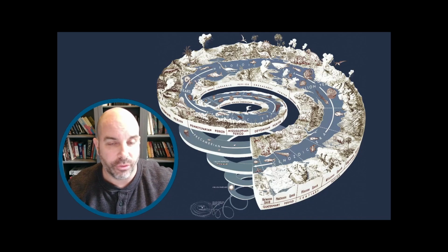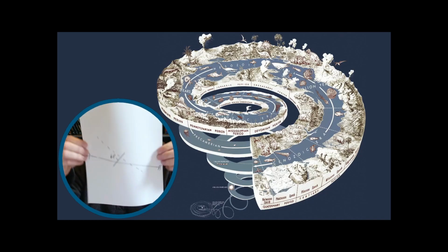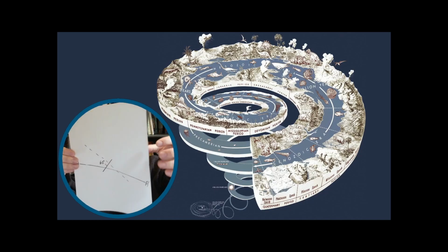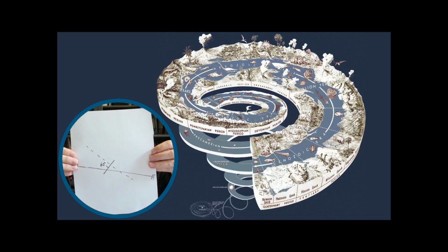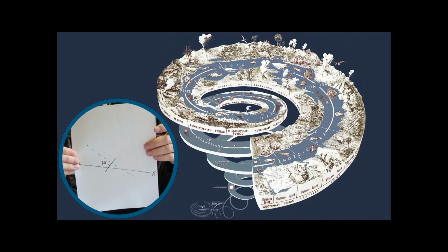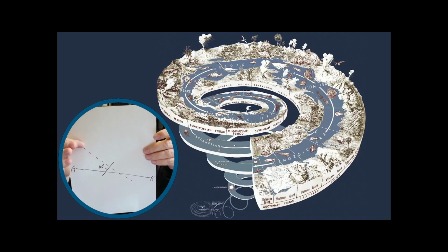So for example, here is a little sketch. Here is a measurement of 210 degrees, 60 degrees, assuming that north is up on the page. Ideally, we would draw a cross section along this dashed line. Notice that it's perfectly parallel to the dip direction, or perpendicular to the strike.